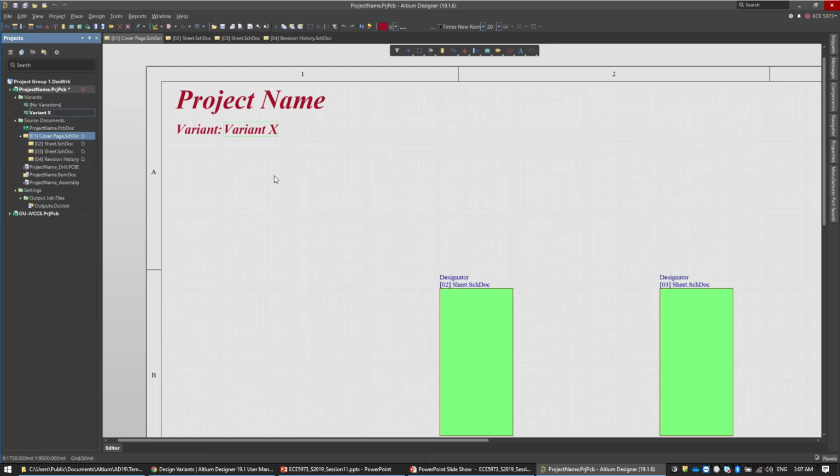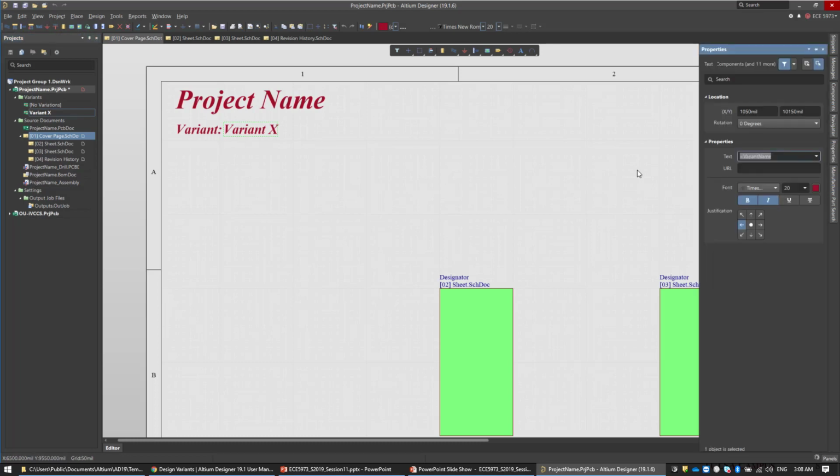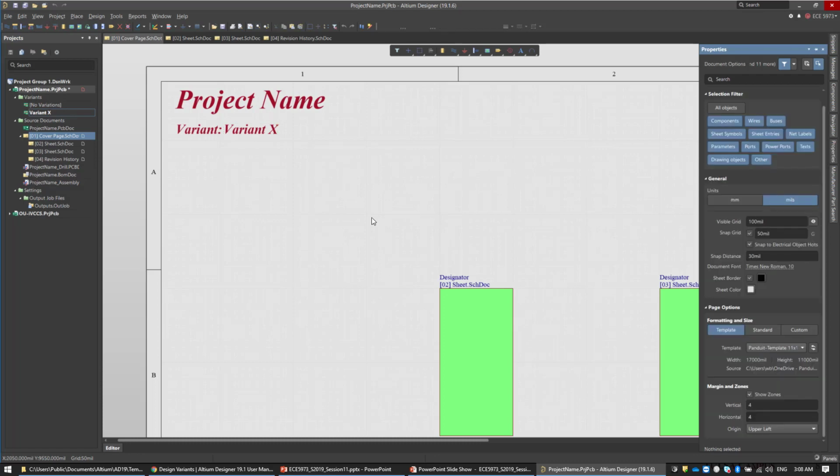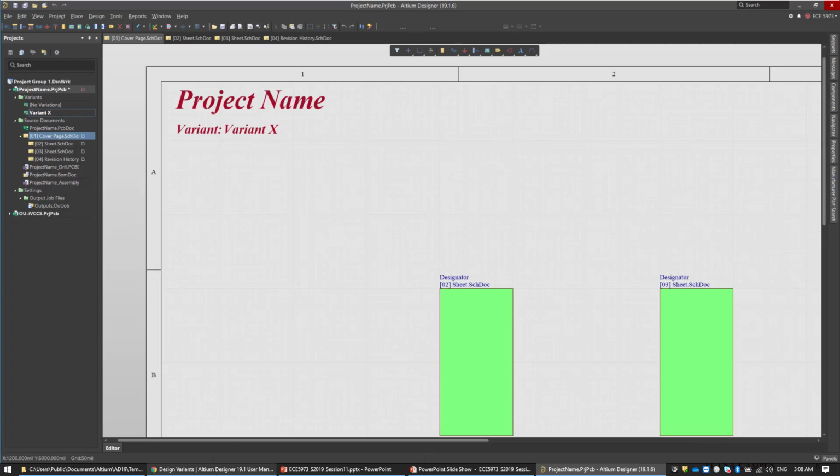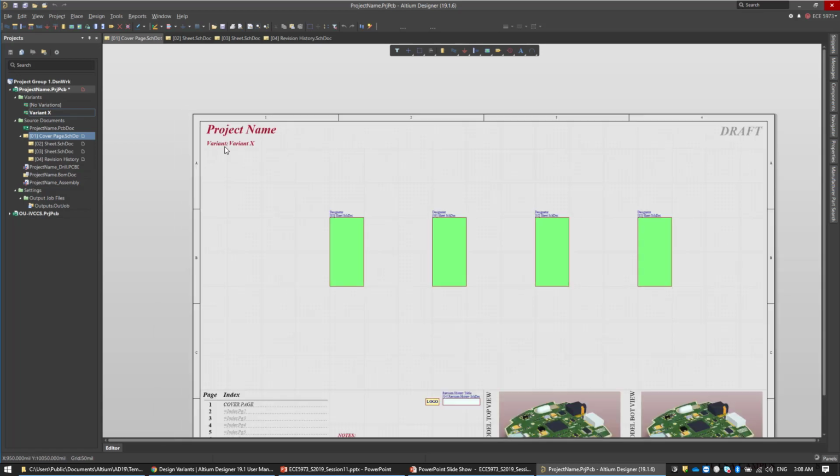This is very, very important. When I give the schematic to an engineer, I say, okay, this is the schematic for a variant model A, for let's say 128 gigabyte memory. So this will print it. The name for this variant is equal variant name, and you can go to the list I showed you in the Altium documentation on the web, and you will see this variant and it will explain it. That's why it's very important for you to go over all these special strings and see the description of them, because they are very handy.